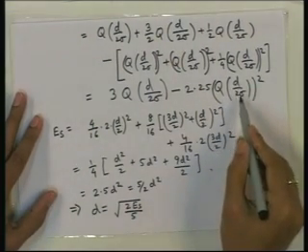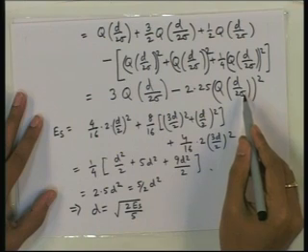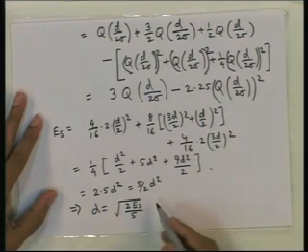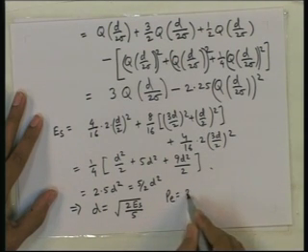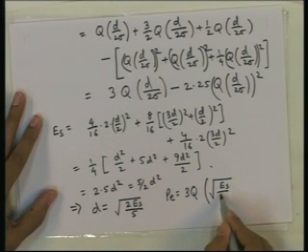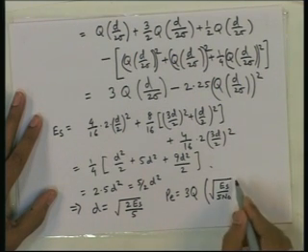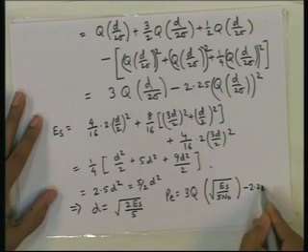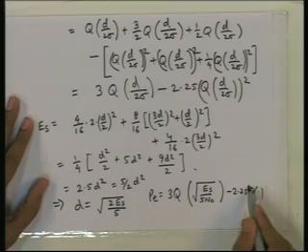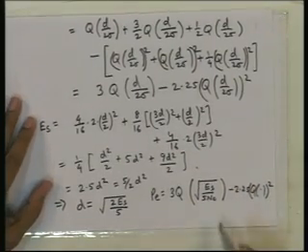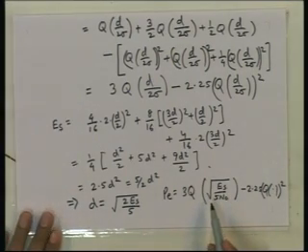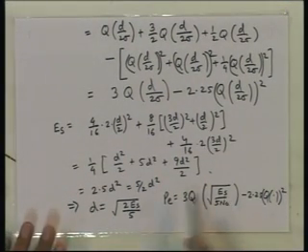This d by 2 sigma term, now the sigma is root over n naught by 2. So the probability of error becomes 3 Q root over E s by 5 n naught minus 2.25 times the same quantity Q, whole squared. So, instead of expressing the probability of error in terms of d, we express it in terms of the average energy of the signal set.